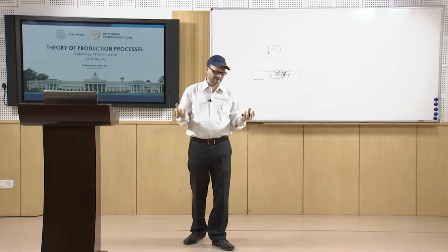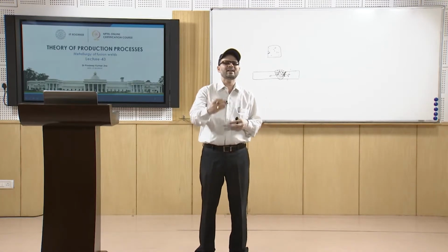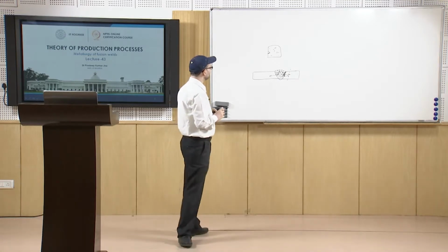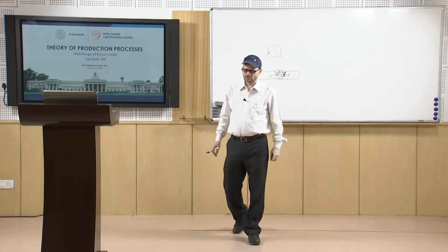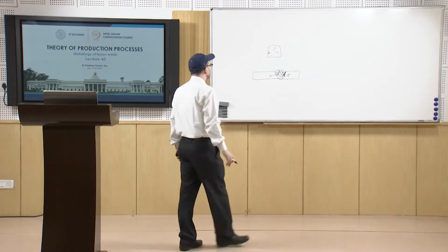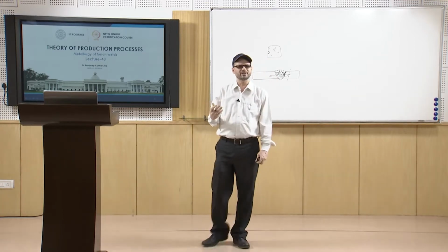Based on that, you will have the undercooling, and then the solidification starts by the mechanism of nucleation and then further growth. Now, in the case of welding, as we discussed, some part of the parent metal is also melted.